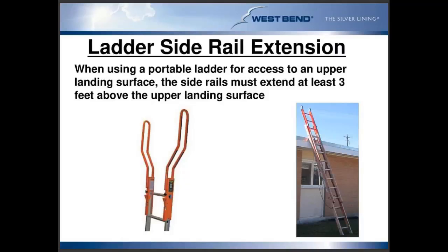But you could take it a step further, where this contractor actually painted the 3 rungs red to make sure that they have the 3 feet they needed. Now, again, I'm not telling you to go out and start painting your ladders red with the top 3 feet, because you might be hiding defects, but it's something interesting that I've seen over the years.